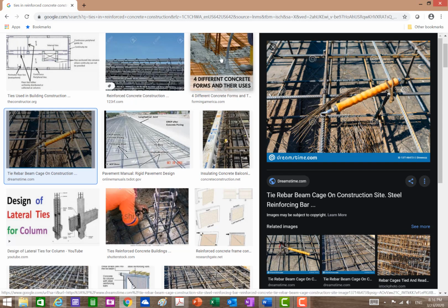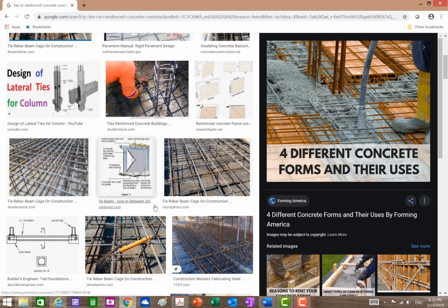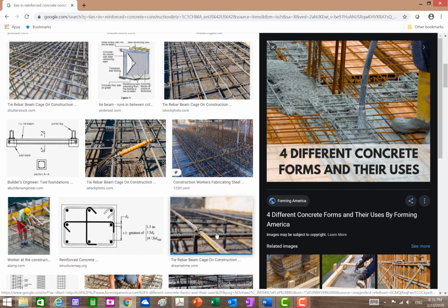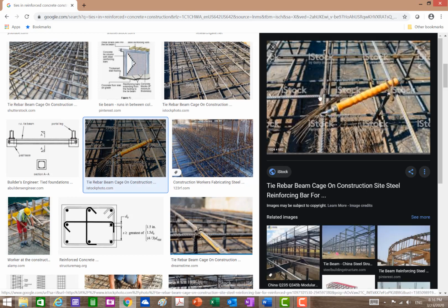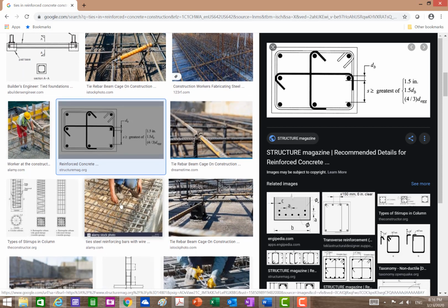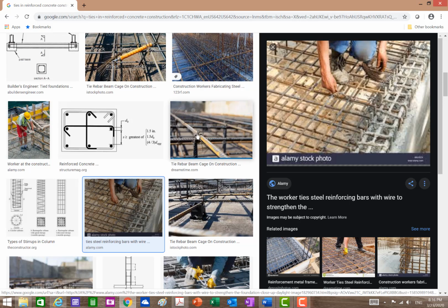Otherwise, when you start pouring the concrete, if you don't have this tie, things move. This creates a lot of pressure. So definitely you want to have those. And that shows you, I think, the best on that. Okay? So don't confuse these elements, which are the tying, just to tie the bars together, with what we've been calling ties in columns, or stirrups in some cases. So those are different. The tying is done simply with wires, just to keep things attached so they will not move.